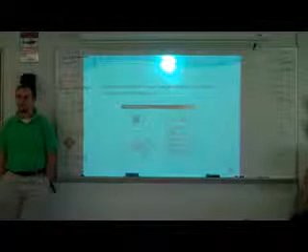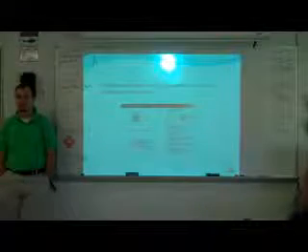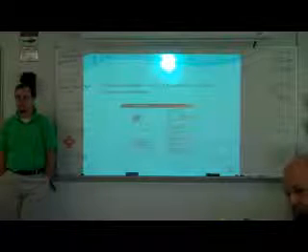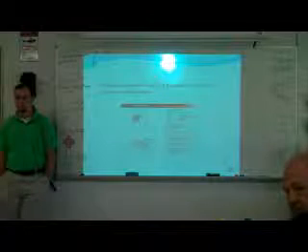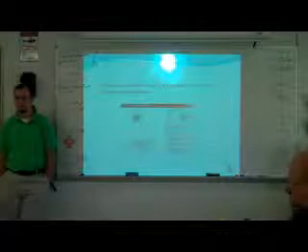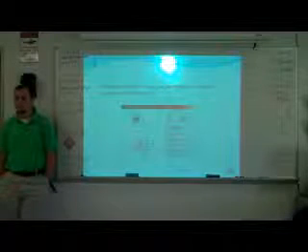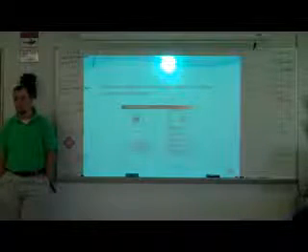Is it readily accessible? If you had to, could you find it in the dark? Well, I mean, you open the door and it's right there. There's nothing in the way of it. If you just open the door, it's right there on the opposing wall. And then the air handling unit's on one side, and the hot water heater is on the other side. It has to be readily accessible. Meaning, behind doors, it's not readily accessible.